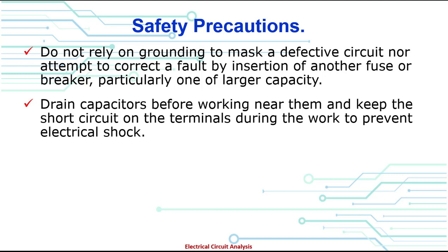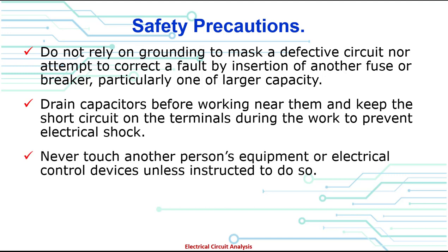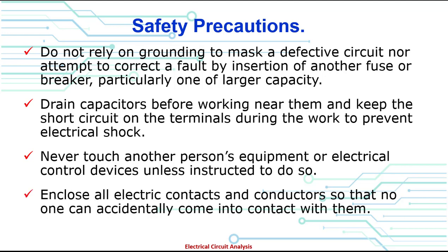Capacitors, you have to drain capacitors because capacitors are energy storing devices. So you have to drain capacitors before working near them and keep a short circuit on the terminals during the work to prevent electrical shock. Never touch another person's equipment or electrical control devices unless instructed to do so. You also have a responsibility to protect others around you.